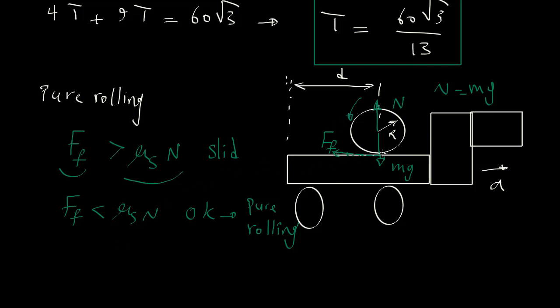So when we were writing down the kinematic equations here, we should add the acceleration for sliding for this point in the horizontal direction. So that would add one unknown to the set of unknowns that we had. So we had the acceleration for this point A slid, that is unknown. We don't know how much sliding we have.